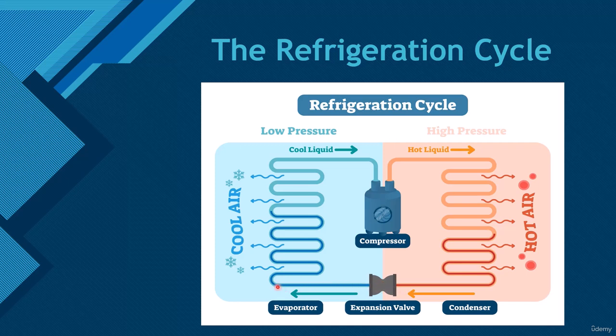And then it goes through the evaporator, a cold gas liquid vapor. Now, by the time it gets up to the end, it's going to be all gas. Here you've got a little liquid, but then as that heat is being absorbed, it'll turn into a vapor. And then here's where the blower fan blows out the cold air, and then it goes into the compressor as a cold vapor, and then comes out a hot gas. So it just continues that cycle as the system is running.